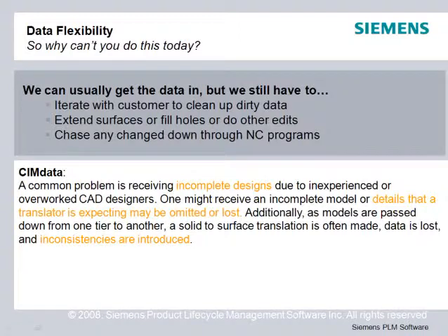These multiple data sources sometimes carry overlaps or gaps between surfaces, twisted surfaces, missing details, and so forth. Model edits are required to clean up these kinds of data issues. Also, model edits can improve the programming process by removing non-machined features or providing surface extensions and other guidance geometry. And no matter the edits, the NC program still needs to be able to update.